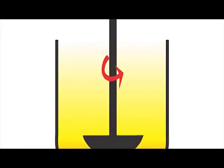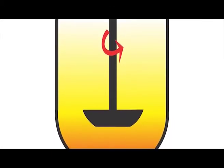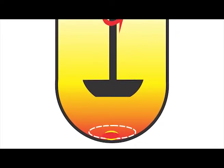Apart from these, there are some more factors related to the agitator which may affect dissolution, such as position of the agitator and sampling probe position. According to USP and National Formulary 15, the axis of the stirring element must not deviate more than 0.2 mm from the axis of the dissolution vessel.